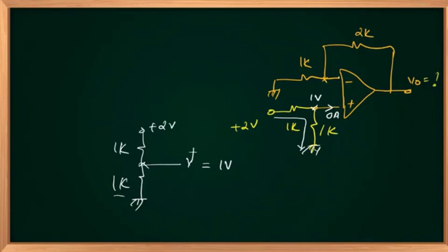Then negative feedback, V plus equal V minus, 1 volt. 1 minus 0 by 1K, 1 milliampere. Finished. Current through 1K. Same current flows through 2K, 1 milliamp. Voltage across 2K will be 2 volts. Then in the polarity given, if you are subtracting 2 volts from your V out, you should end up with how much? 1 volt. So V out should be how much? 3 volts.